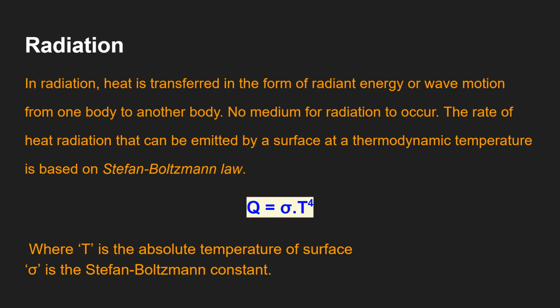and it is the only means of heat transfer between bodies that are separated by a vacuum, as in space environments. And now this convection, which you have seen in the previous slide, and this radiation are the principal means by which heat is transferred to the ambient air. In general, approximately 70% of the heat dissipation from electronic equipment might be through convection, and 30% through radiation. Moving on to the next slide.